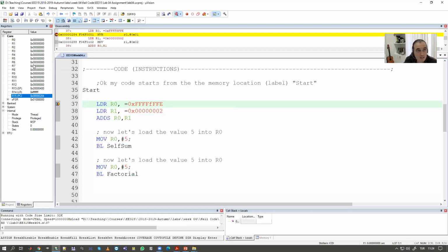Is it really? Well, I've got the live values of R0 and R1. If I just take one step forward, I can see it. How to take one step forward? You can do it many ways. You can put another breakpoint here and say jump. Or there is this F10. It means step over, get to the next line.